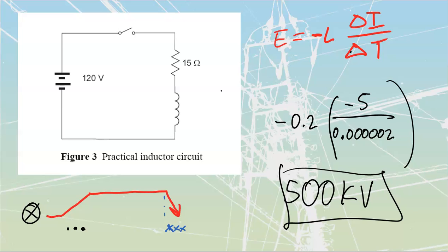Can you find the value out of it? They say calculate the inductive coil that produces a back voltage of 400 when the current changes from 80 to 30 amps in 0.1 of a second. If you go through that one, you should be able to figure out your change in current. It's going to be negative 50 amps over top of 0.1 of a second, and then just from there, work everything backwards. It'll come out to the 800 millihenries that we're going to have.